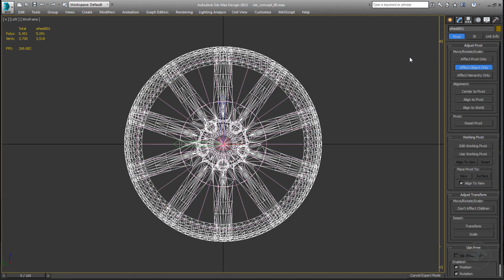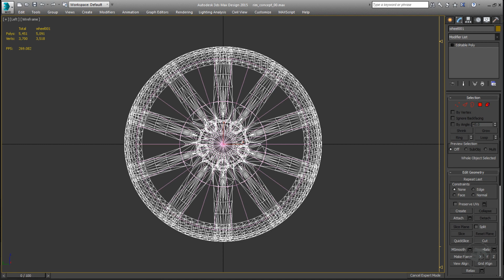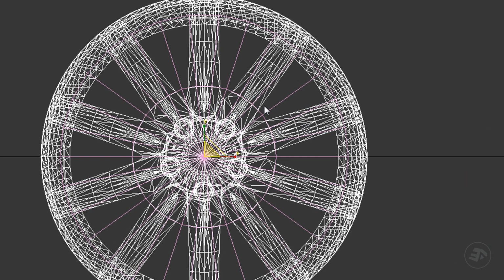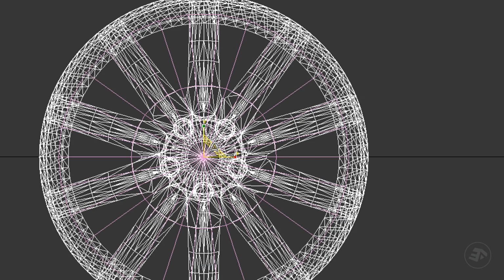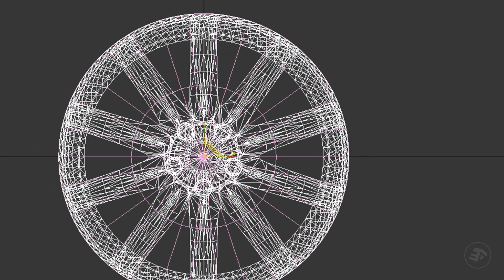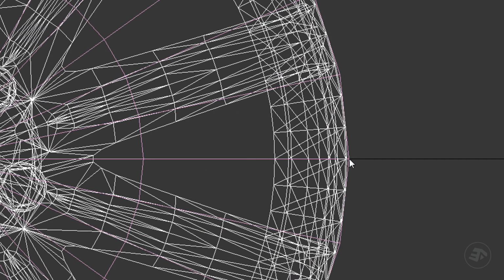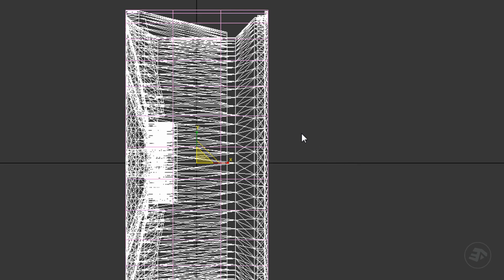Now, let's scale down the reference rim to match the size of 21 inches. For that, I use the Uniform Scale tool with View as reference for the coordinate system. And of course, the Scale tool is at the center of the object. In the left viewport, scale the object in between the XY axis. That will exclude the Z axis from the scaling operation. And keep the width of the rim unaltered.